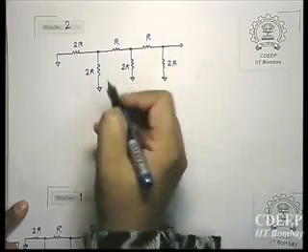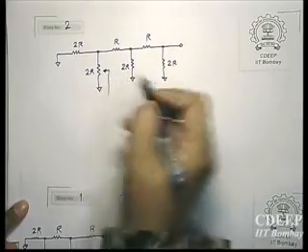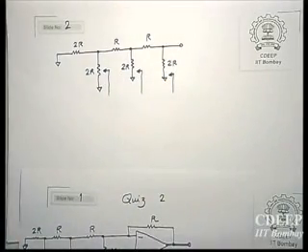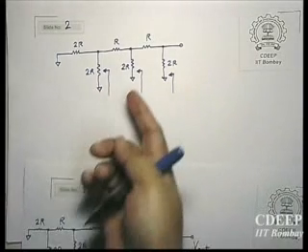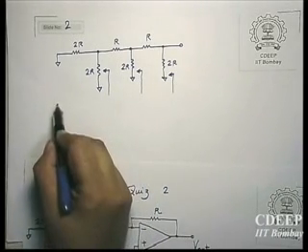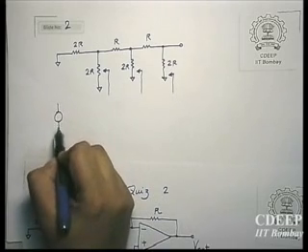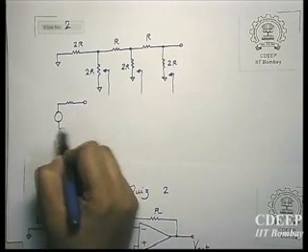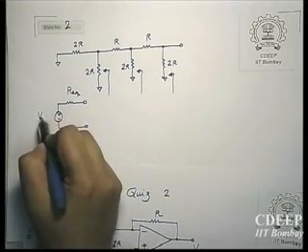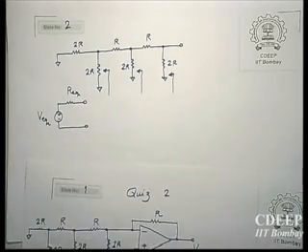So always you start, draw the equivalent Thevenin of the circuit. Start from left, come to right. If you have some points which are connected to V full scale, then not only the equivalent resistor, the equivalent open circuit voltage also needs to be included. Therefore, always you will have a circuit like this. This is your R equivalent. This is your V equivalent. Then the analysis will be very simple. So now you do it for two cases.